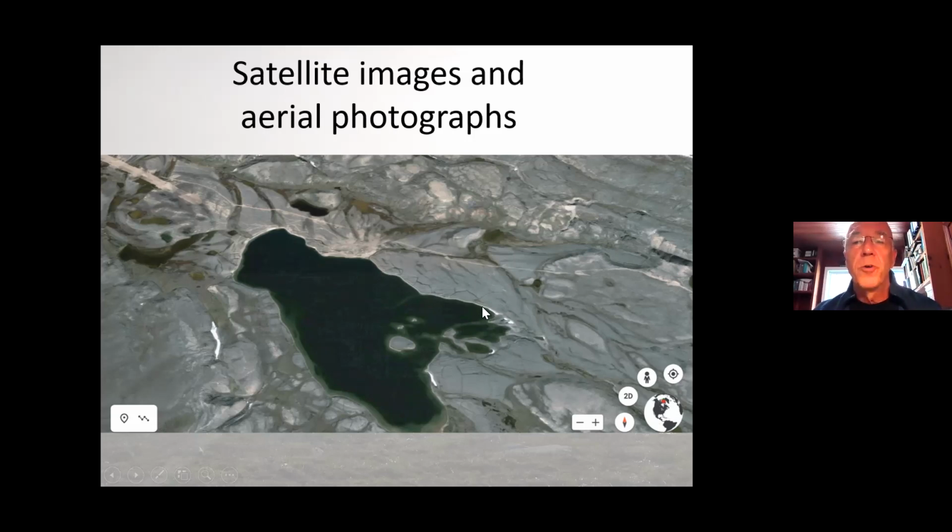Outwash deposits are granular material, a very good source of gravel if you're building, but they can also cover buried ice. So something to be worried about. You can see here the braided channel, and these types of channels indicate that there's lots of granular material in there, and it's generally good quality gravel or sand that can be used for construction. It can be a good foundation for something. You can also see that there's lots of ice wedges, probably some buried ice under the trough of the wedge. You can also probably see that there's finer grained material here, a lacustrine deposit.